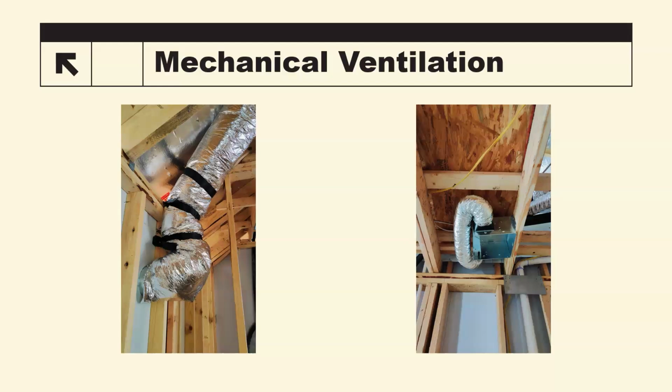And then, of course, the photo on the right is the exhaust fan. If you're using this as mechanical ventilation because you're on the dry side of the United States, this always works out to where the electrician installed the box and the HVAC guy has to run the duct. So the electrician installs it to run the shortest amount of wire, and now the HVAC guy is left with having to run the duct backwards or at 180 degrees or something. This fan, probably an 80 CFM fan, if I could tell by the way the box is deep, and it's a 4-inch duct, and I can see it running up to the right, which means it's probably going to be a kind of lengthy run. That's probably not even going to push 50 CFM looking like this.